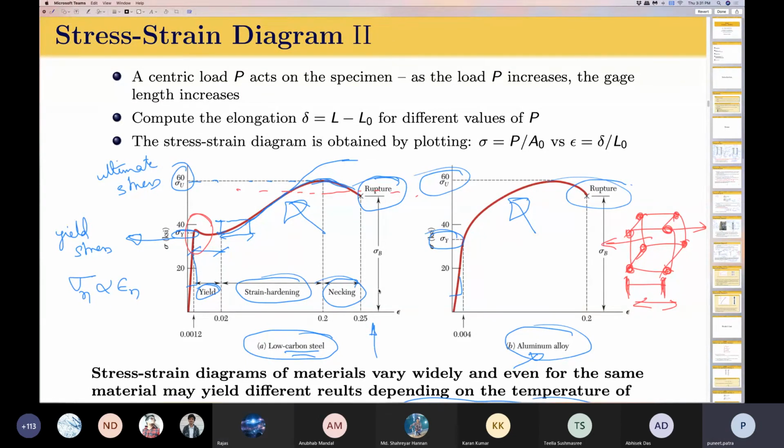Any other question? Yeah, go ahead. So the stress created is actually due to increase in the potential energy of the configuration of atoms. Correct. But we are not going to the atomic level. That is significantly more advanced for you right now. I personally work at the atomic level, so I know a little bit. So from that side, I'm saying that the increase in stress is occurring because your atoms are basically trying to come to a new equilibrium potential energy minimum configuration under the application of the forces. That's all you should take as the message from this discussion.